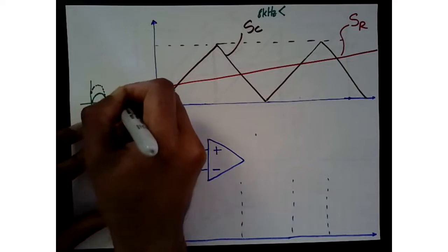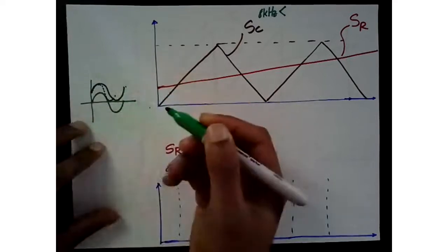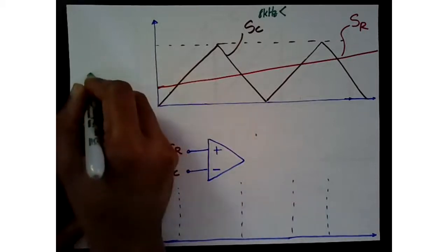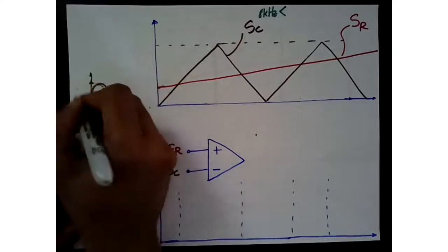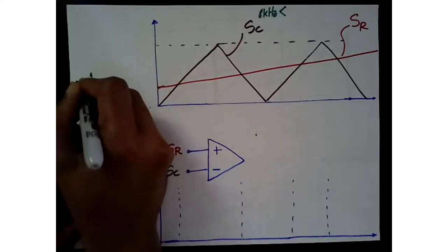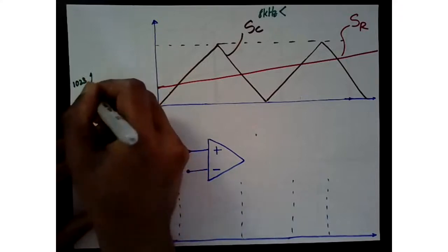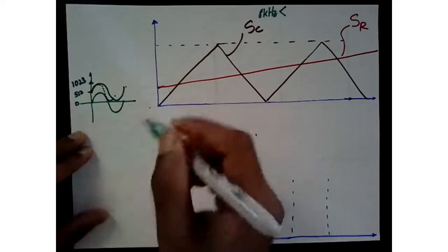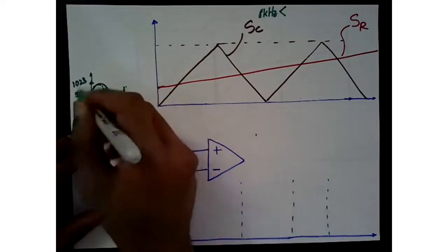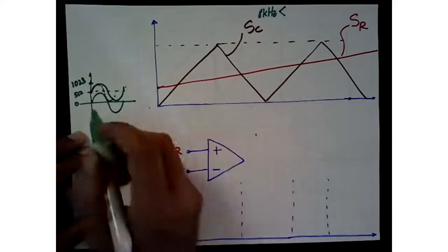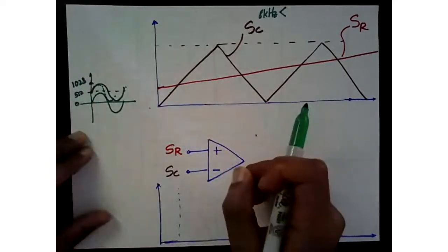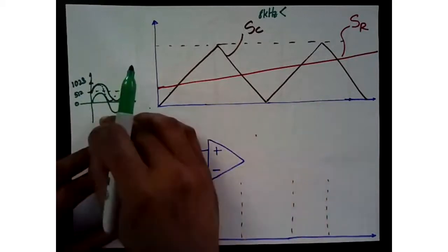Everything is implemented in the digital domain these days, so your signal could vary from 0 to, let's say, 1023, and then the halfway point is 512 counts. That's typical in terms of binary, because you have 2 to the power of the number of bits for your register. That's how you determine how much peak to peak value you set.